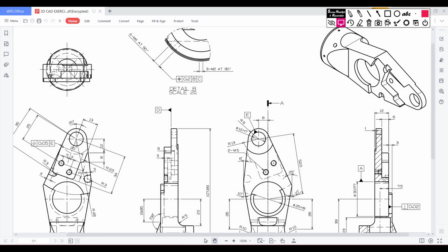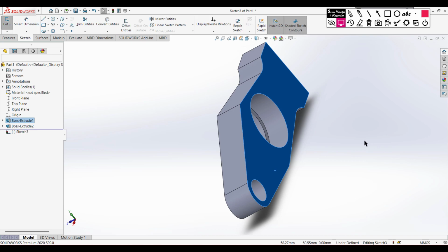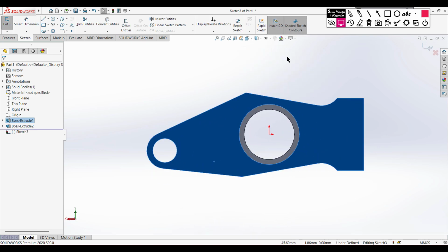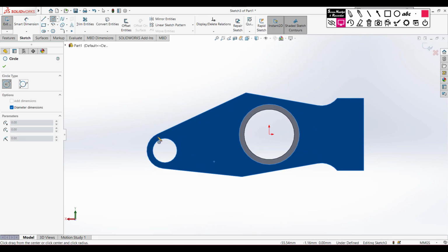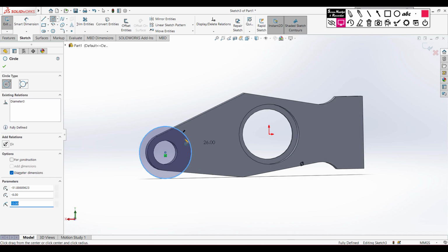So let's do this. I am selecting the back face, now sketch, now normal to it, now select a circle and place the circle to previous circle origin. Okay, now draw a circle of 13 radius, 13 multiplied by 2. Now isometric it for a better view.